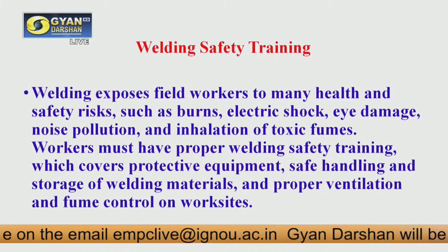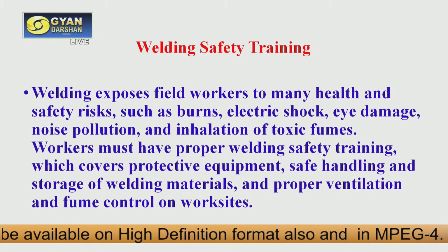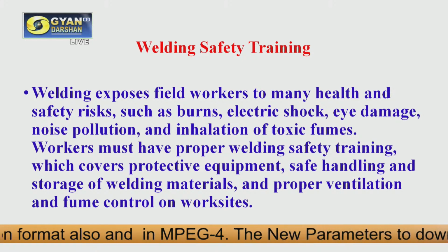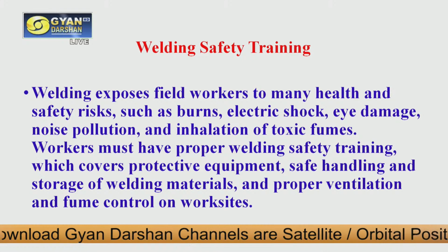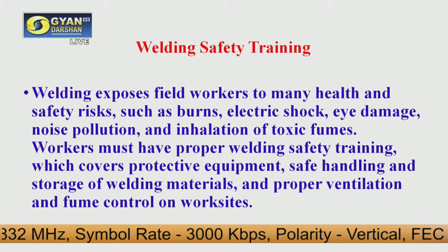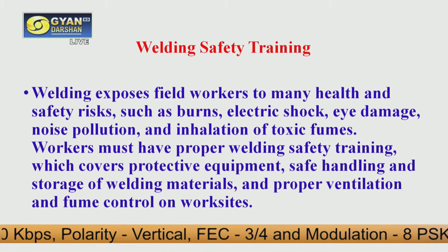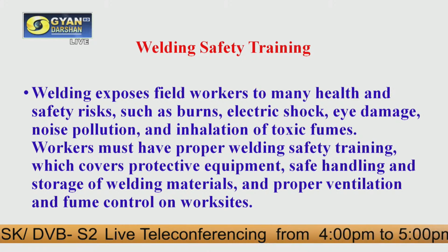Then as I told you, eye damage is the biggest challenge in welding work. Along with this problem to the eyes, there is noise pollution. It creates noise also. And along with that, some toxic fumes are also created while doing the welding work. If workers inhale these toxic fumes, it can create problems to their health, especially to the respiratory system. So they should protect themselves from these toxic fumes. All these should be trained to the workers. Also the workers must have proper welding safety training, which covers protective equipment, safe handling and storage of welding material, and proper ventilation, because if you have proper ventilation, then you can easily avoid the problem of inhalation of the toxic fumes.